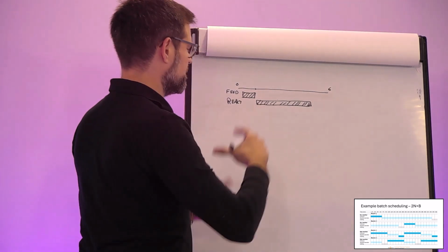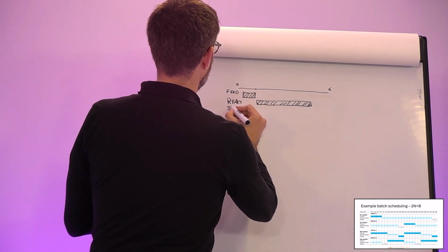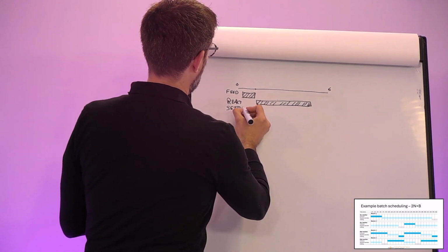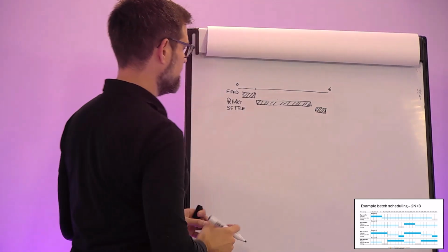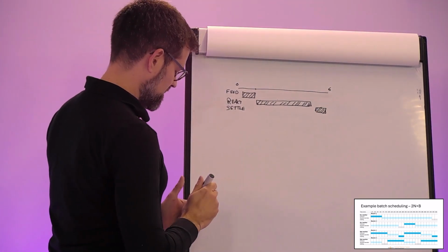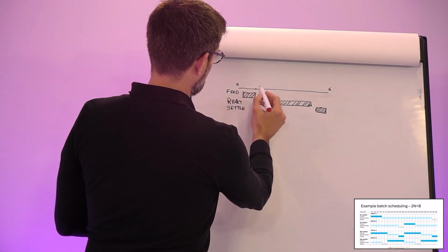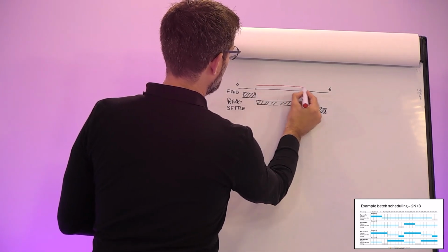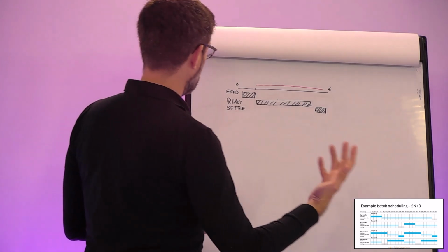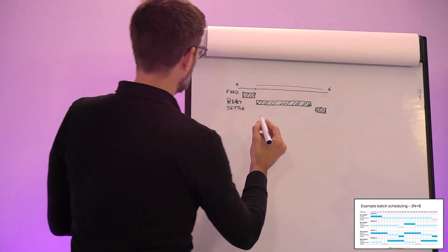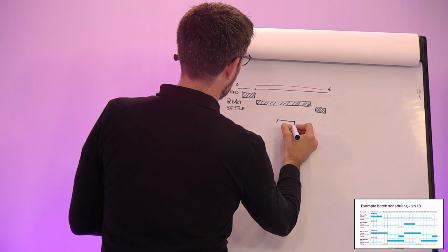And then you have your stripping and settling phase. And stripping we will come to later in this course. We call this the settling phase, settle, and that will be at the end of the cycle. And this will be during dry weather, a typical setup, how we do it. As you can see already here, if you have that feeding phase in this part of the cycle, we don't have a feeding phase. So we need a second reactor or a buffer to put the influent to. So you have a second one running also a feeding phase. And that can start here with the feeding phase.